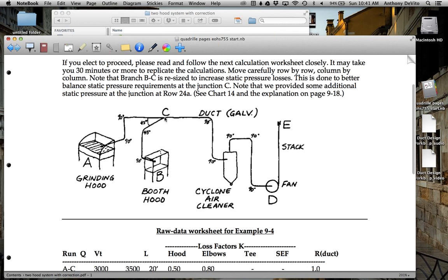So we needed to adjust the diameter of this ductwork so that we got a higher velocity and a lower static pressure at this point. We experimented. We changed the diameter of this ductwork until we got the 2 calculations for static pressure to be within a ratio of 0.8 to 1.2, between a minimum of 80%, 20% low for the branch, or 20% high for the branch. So they were close enough.